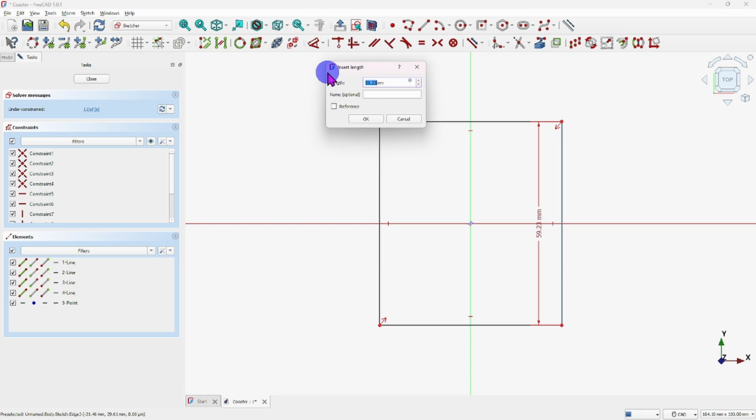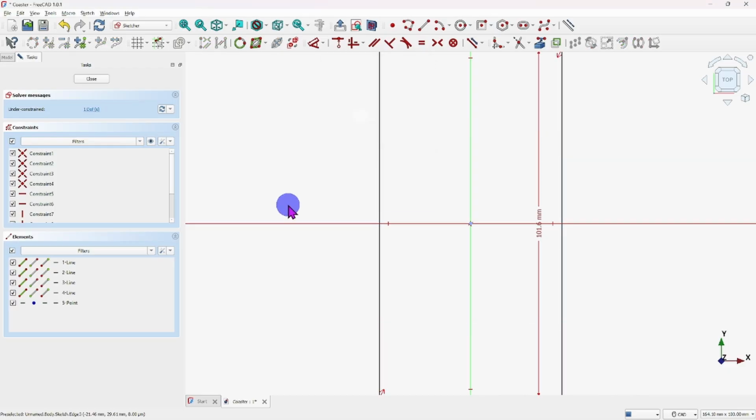I hope that makes sense, because the core programming of FreeCAD is built on millimeters. But for right now, what you can do up here is put inches in, and I'll show you how to do that. Right now, I'm just going to hit the delete key and hold it down until the millimeters go away. There you go, it's gone. And I know that a coaster is about 4 inches, so I'm going to put 4. And you have to use the inch marks or it's going to give you millimeters. So I put 4 inches and I'll hit OK there.